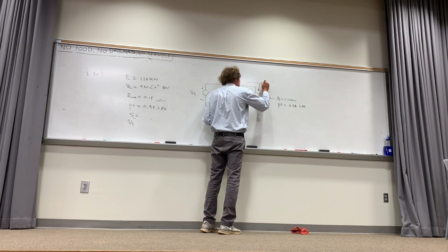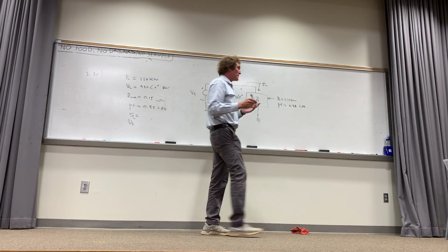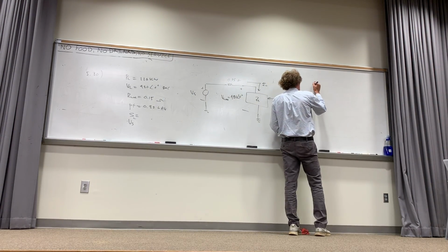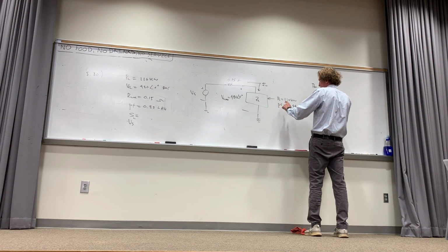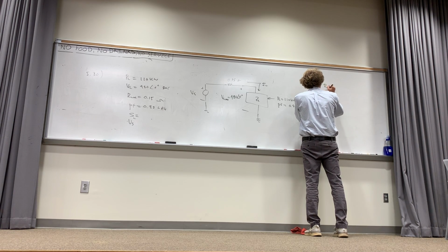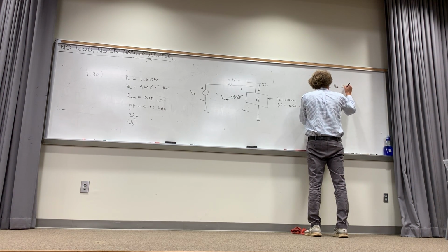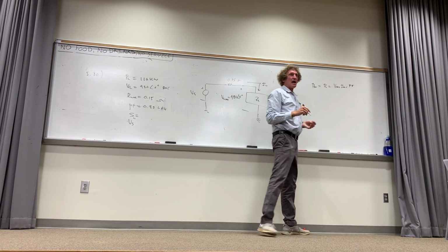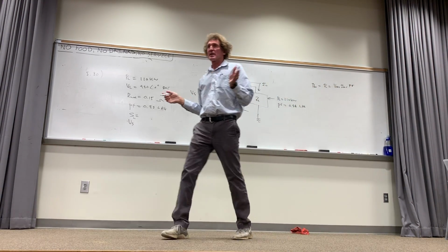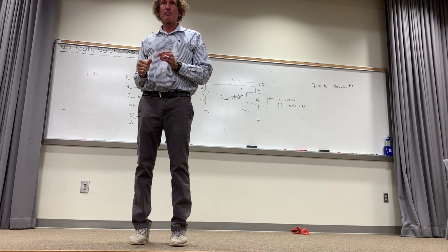That's the key to all of this. We want the line current right there. The way we get it is, we remember the equation that average power, P load, is equal to VRMS times IRMS times the power factor, which I'm just going to abbreviate as PF. I know it's the cosine of theta V minus theta I, but I'll just abbreviate it PF. Is everybody all right with that?